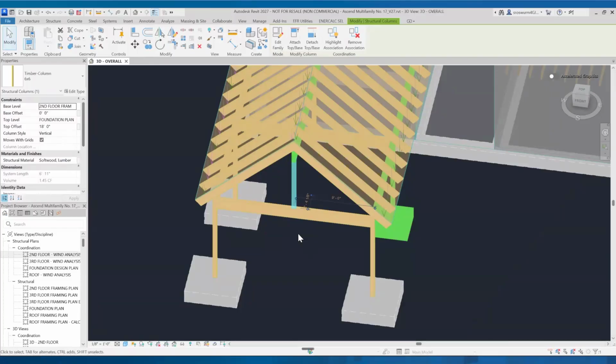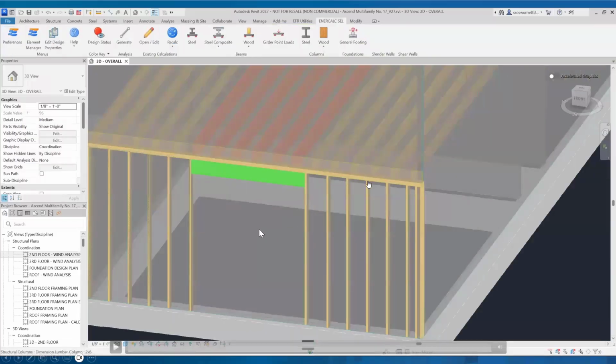So if you had a situation where you've got heavy loads on a wall and then the wall lands on something else, you can basically synthesize that effect by inserting a dummy stick frame like a stud and then transfer axial force down from level to level, if that makes sense. And that's really what the transfer post feature is all about, so that you can synthesize those more unusual conditions.